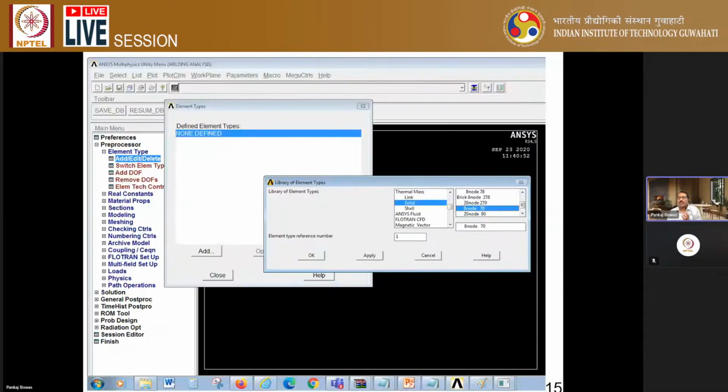What I'm telling, understand? So for different types of thermal analysis, different types of formulation, researchers have made them and put them in different types of folders. For thermal analysis purpose itself, there can be a different number of thermal elements. So for our case, we are going to do three-dimensional thermomechanical welding analysis for prediction of residual stress, thermal history, as well as distortion.